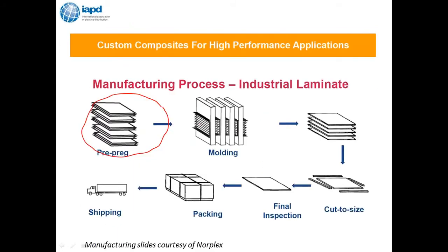Each opening is going to have your bologna sandwich in there. You then put it under pressure and heat. It ramps up to a very hot temperature, then it ramps down over a particular cycle for each kind of grade of laminate. And during that process, everything bonds together.